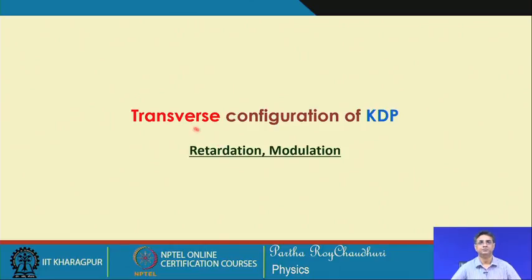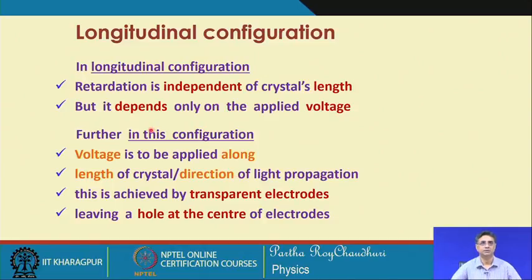Okay. So, the transverse configuration of this KDP crystal: we will look at the retardation and modulation aspects under this configuration. In the longitudinal configuration, we have seen that the retardation is independent of the crystal's length, because you have V by L, which represents E_z, and you have the length of the crystal L. So this L and L cancel.